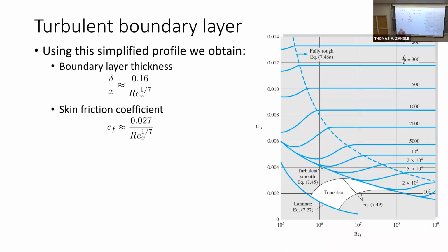The drag that we get on a little square here on this table is different than the drag that we get on a little square here on this table, right? Because the boundary layer is different as we move downstream. That's captured here. So the skin friction coefficient is like what the local drag is, the drag on one little tiny piece of the plate. That's what's described by the skin friction coefficient.